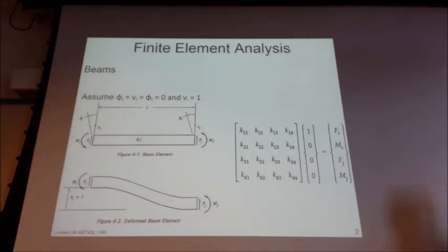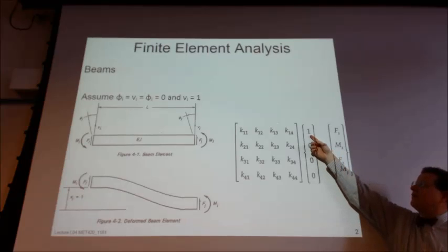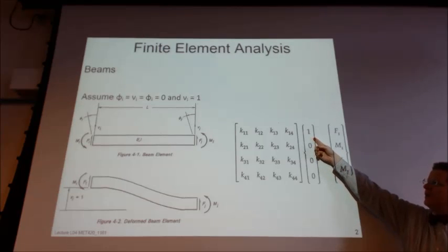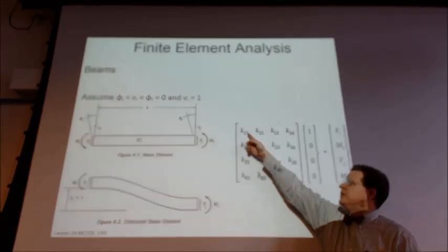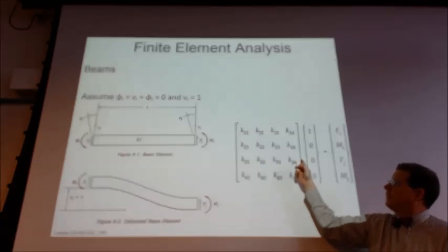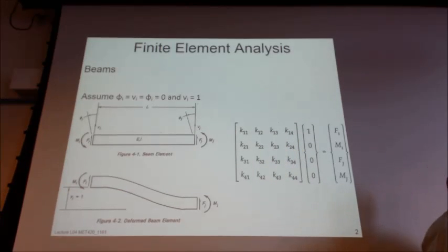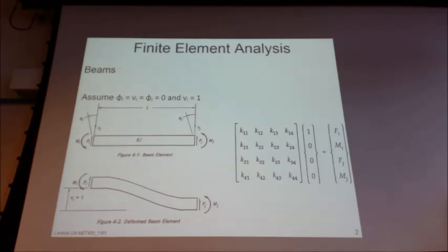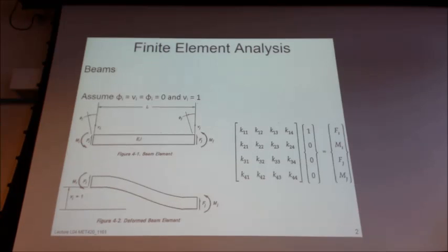Then from our matrix, right, if we have our displacement at 1 or a unit, then we know that we can determine what the equations are for these columns or that column, and those will all go to 0, right? And so we're just dealing with one part of our matrix at a time. So we can get a value for F1 and M1.